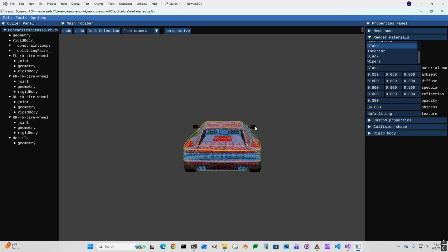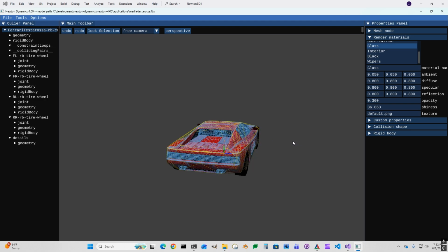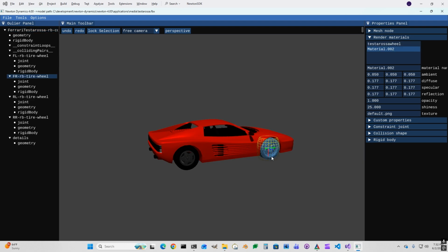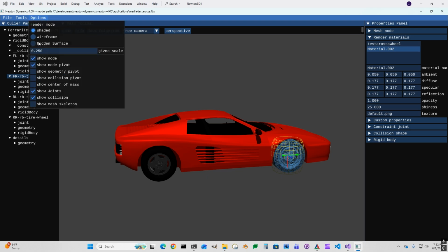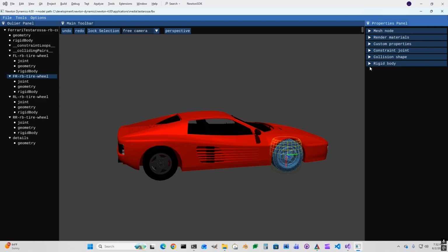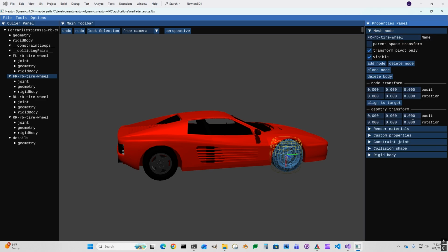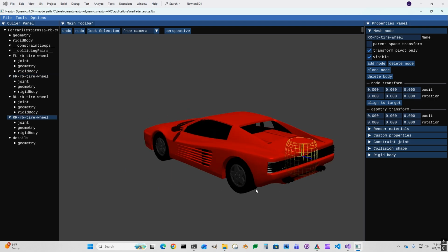We then inspect the imported model and verify that all collision shapes have been generated correctly. We observe that the chassis collision shape is correct, but the tire collision shapes are not. To fix this, we apply a pivot rotation to each tire so that their local axes match the convention expected by the physics engine. Specifically, the x-axis should be perpendicular to the tire plane and the up-axis should be aligned with the chassis up-axis. We do the same to the 3 remaining tires.